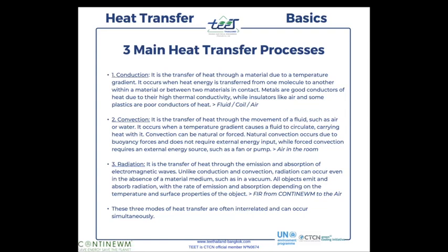So this is a written way to say what I was saying. Conduction is the transfer of heat through the material due to a temperature gradient. The temperature gradient means you have one side that is hot and one side that is cooler, different temperature. It occurs when heat energy is transferred from one molecule to another within a material or between two materials in contact. This is very important. The conduction happens when you have two materials in contact.